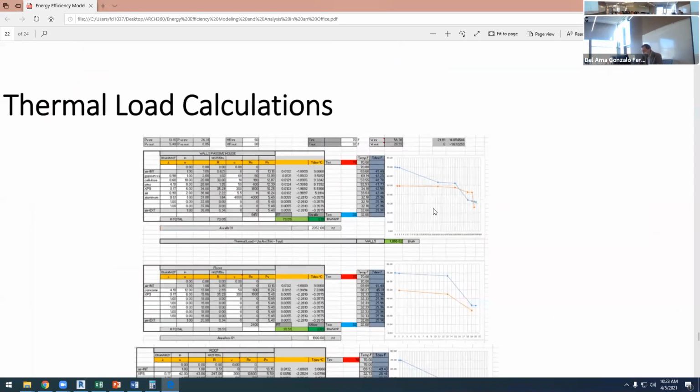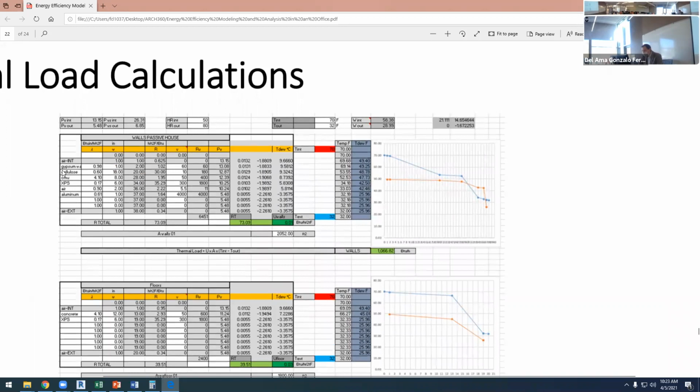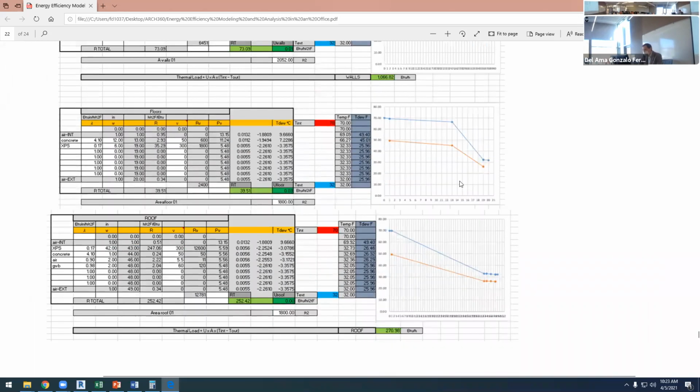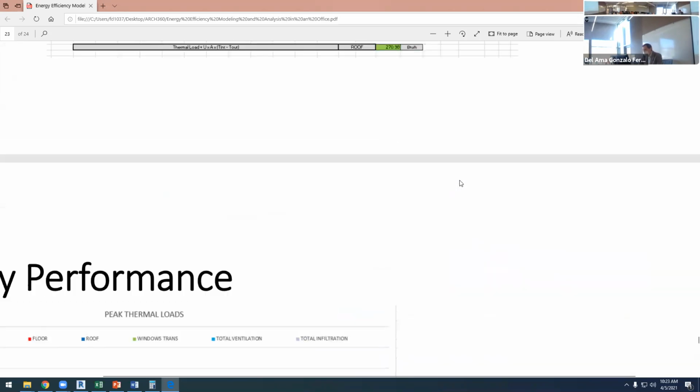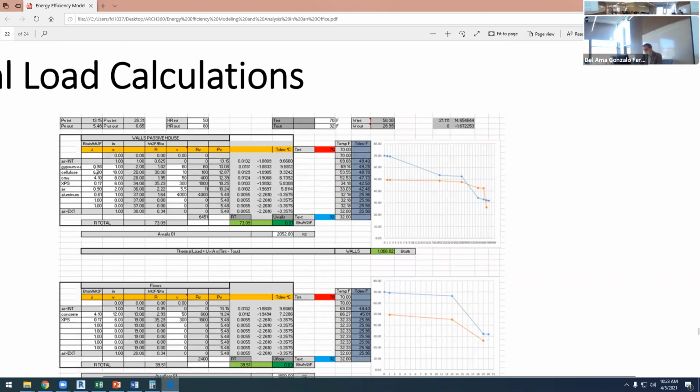And then we have this, yeah, you're using cellulose, and as it was expected, if you're using cellulose, we have a condensation risk. Do you mind including here a vapor barrier to try to avoid this? And show me both. The R value won't change, but the condensation risk, if you add a vapor barrier here inside the cellulose, I'm sure it will change. So you will reduce the condensation risk.